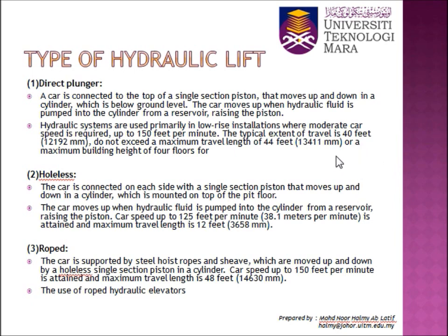The car moves up when hydraulic fluid is pumped into the cylinder from a reservoir, raising the piston. Car speed up to 125 feet per minute is attained, and maximum travel length is 12 feet. Okay, and next type is rope.